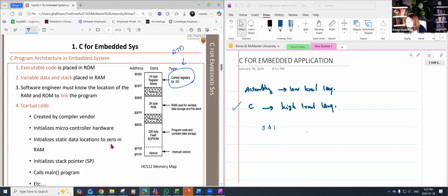So some parts of the memory addresses are assigned to this control structure. Some parts are also assigned to nothing, like in here. This is a little bit of the memory structure which is assigned to nothing. It doesn't do anything. It's just right in there. So nothing is a very small part of the memory to specify the range of the memory. And of course, most of the time, right after this one is the RAM. In here, I'm having like 2 KB RAM.